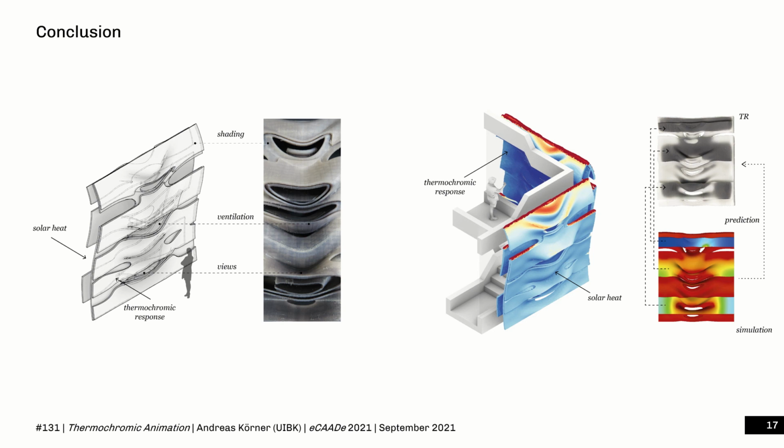To conclude, a combination of digital simulations and material experiments can be used to configure the thermochromic response of architectural surfaces. Layers, cavities, and overhangs can affect thermochromic response. By this, surface articulations can visually highlight thermally invisible parameters of thermal comfort over distance. By investigating this through digital design research, the paper contributes to the fields of thermodynamic architecture and digital ornament, with the premise to create a closer interlinkage between material, geometry, color, and texture that extends the formal vocabulary to better communicate between the natural and the built environments.